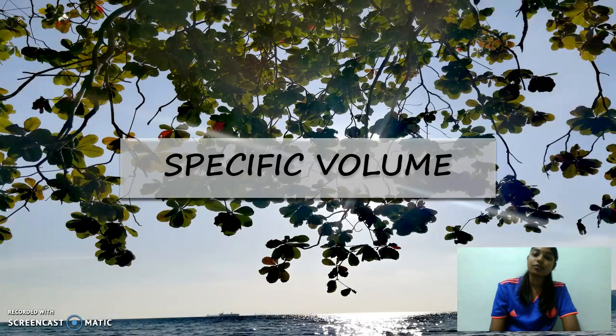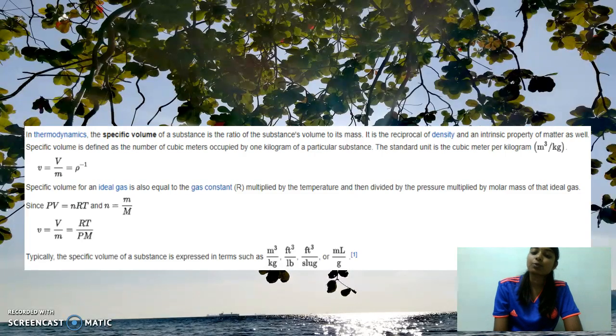Next, we'll look at specific volume. Specific volume is the inverse of density, so it is volume over mass. From the ideal gas equation, PV equal to nRT, we know that n equal to m over molecular weight. So V over m equal to RT over PM. The unit of specific volume is meter cube per kg.